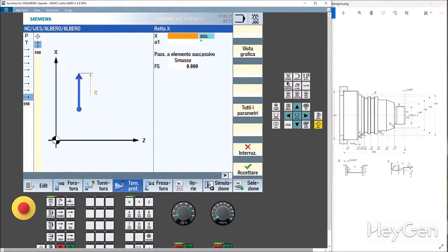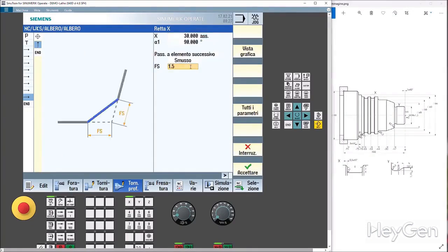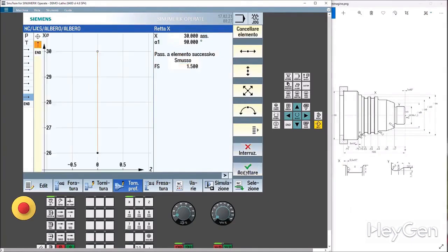I'm moving upwards. Actually, let's go back. I'll show it to you again later. X30. Chamfer 1.5. Vertical move. Machine decides. Chamfer not made. Unknown destination. Left to 17, Z17. Defaults 180 degrees. Chamfer 0. Sharp edge. To X40, radius 2.5. Change to radius 2.5. Enter to register. No radius yet. Next move. X50, Z30. Angled move.